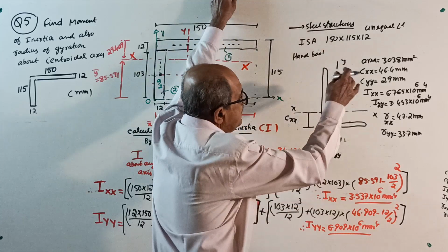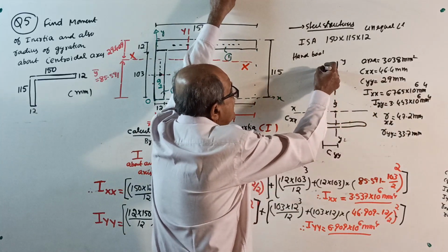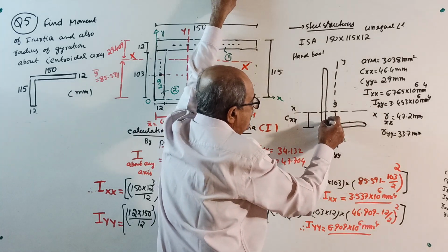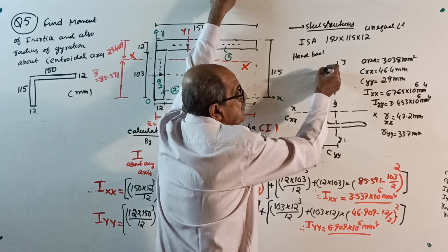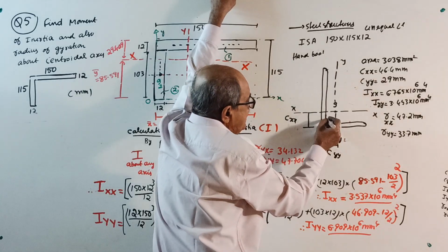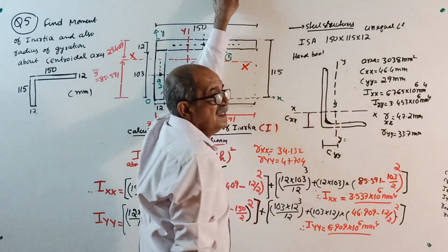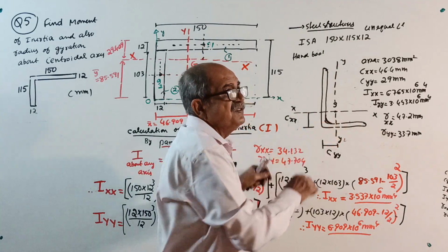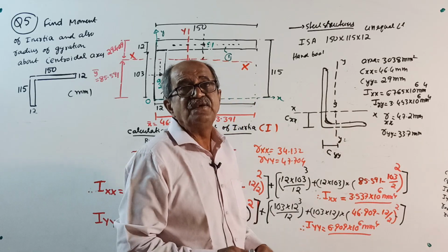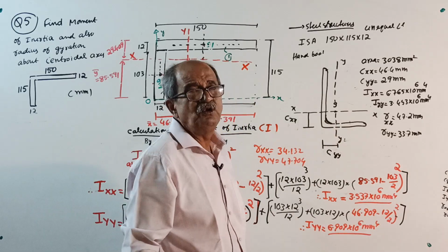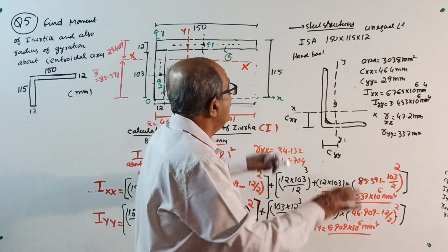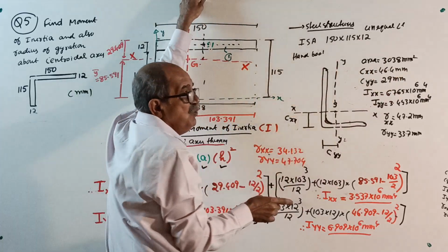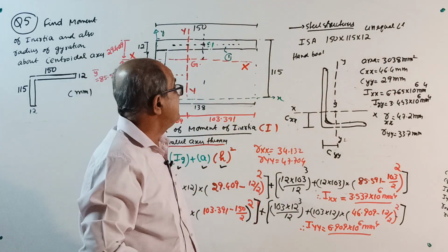But here, when they give this property, they consider some slight curvature, and also the curvature here. A little area here is made flat, and here a little more area. They accounted for it. They even know the radius of this curved part, called the radius at root. All that is in steel structures. Therefore, the values given in the IS handbook will not exactly match this one.